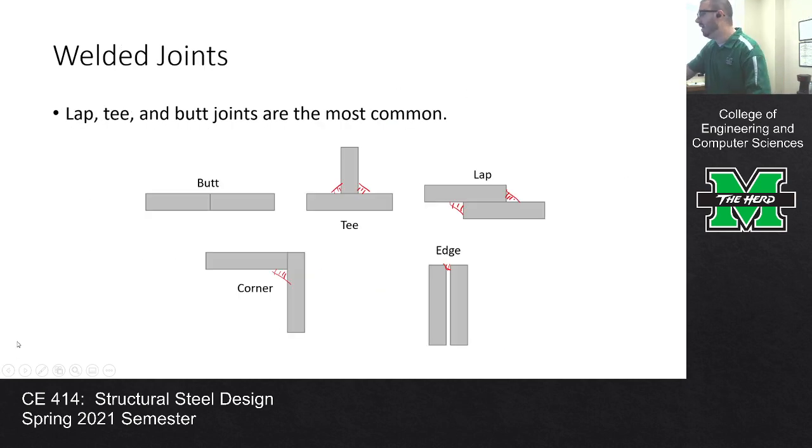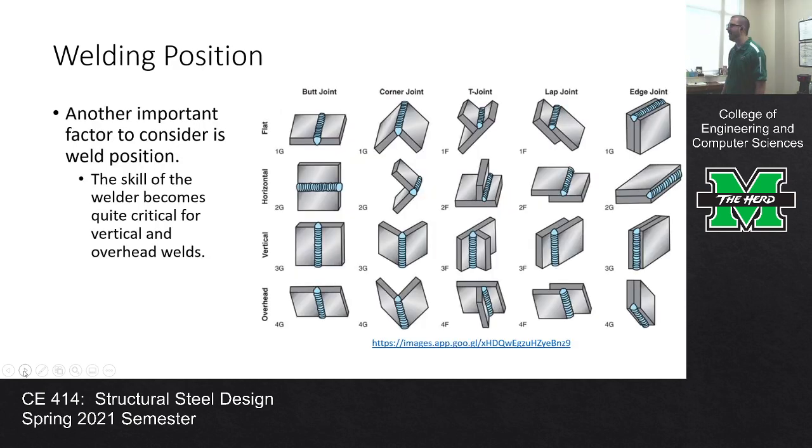How can a weld weaken? Welds on deck look like they've been sheared off. Could have been. Well, there's a number of reasons for that. You could have a weld that just didn't have much weld penetration. It was placed poorly. It was brittle. So there's the quality of the weld. That's the first reason a weld can fail. Welds, by their nature, you are introducing a flaw into the material when you weld something. So that flaw can be amplified by fatigue.